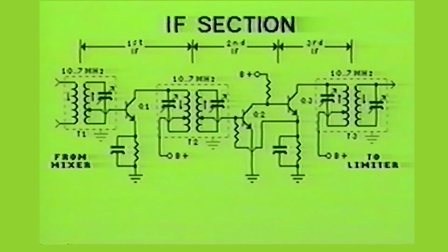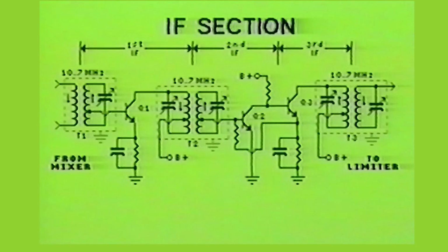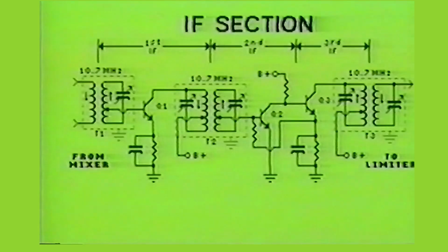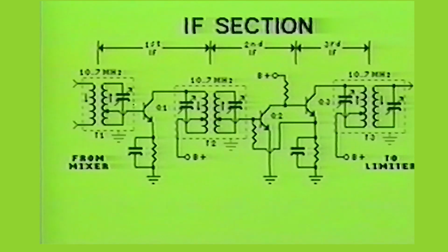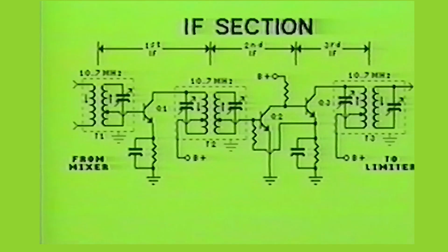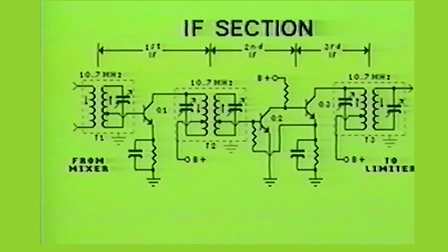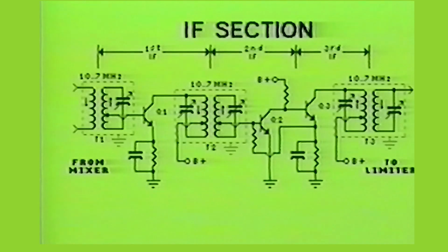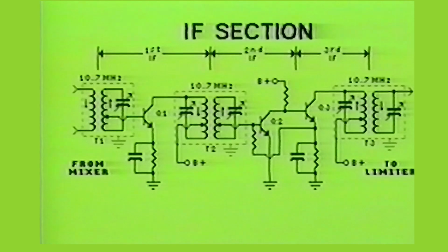Here you see a simplified schematic diagram of a 3-stage intermediate frequency amplifier network. As we have mentioned, the majority of the amplification being received by the incoming signal is produced by the intermediate frequency amplifier stages. The IF stages must not only provide the high gain amplification and selectivity, they must also provide a wide bandwidth. Let's take a quick look at the standard FM IF bandwidth.